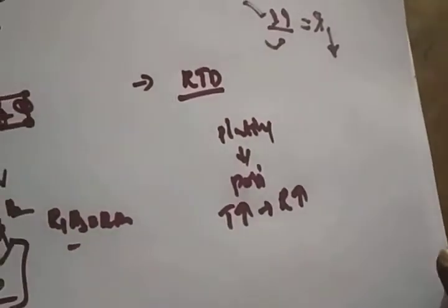So the change in resistance we can calibrate with a scale, which is analogous to the voltage generated from the changing resistance, which is analogous to the temperature. So in this way we can easily find out the temperature. We discussed this in detail in the last session.